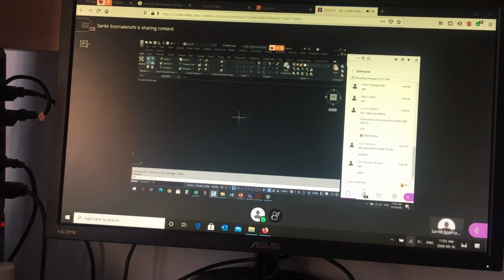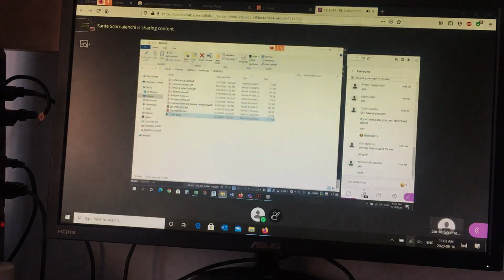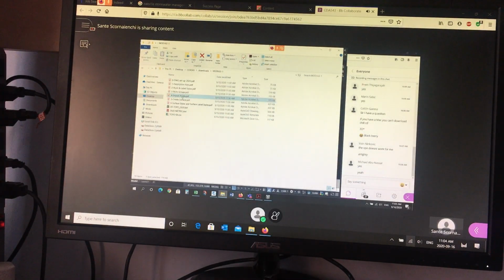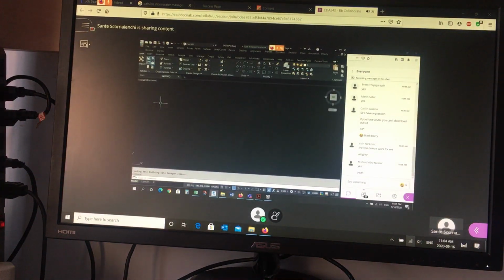Let me import the points. If you don't do anything, okay? If you don't set up anything, okay? And you can see what I'm talking about. So this is how you import points. This is actually function number 4, but I don't want you to do that until you prepare 1, 2, and 3 first. So let me do that, and then I can speak to 1, 2, and 3 and why they're important, why you want to organize yourself with description keys, point and label styles, and groups. Okay, so let me just import the points. So I'll skip those just to show you what happens if you don't.